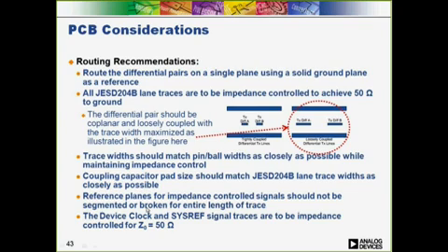Trace widths of at least 8 mils using 1 ounce copper are recommended. If possible, matching the trace width to the pin or ball width will minimize the impedance mismatch where the trace and pin intersect. In the spirit of reducing impedance mismatches, it is critical that the differential pairs are not referenced to a segmented plane, but only an uninterrupted plane. As for the device clock and sysref traces, these should also be impedance controlled for 50 ohms to ground.